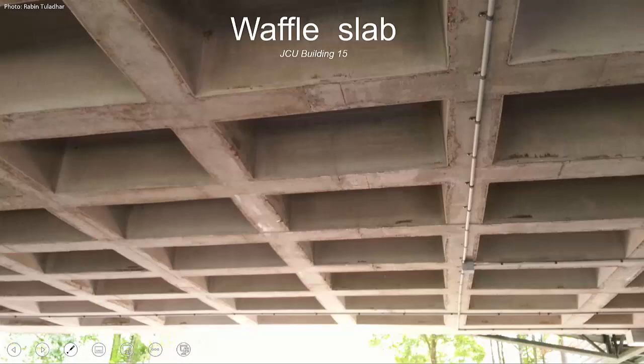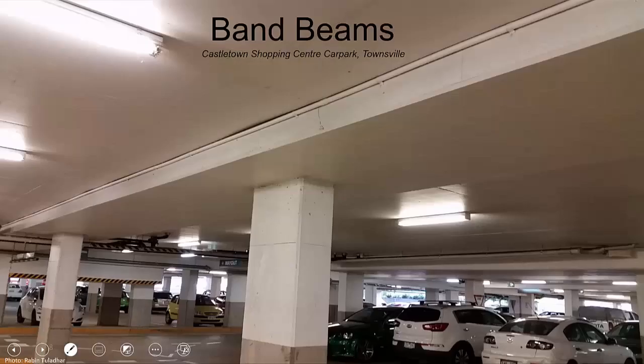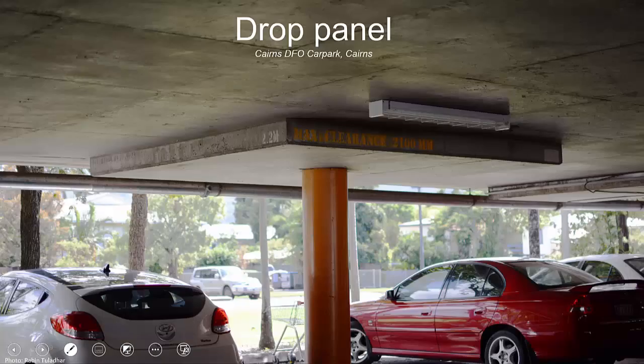However, the formwork for the construction of waffle slab can be pretty tricky. Band beam slab, as you can see here, is used in car parks where the slab is longer in one particular direction. Drop panels, as you can see here, are used to prevent the punching shear effects.